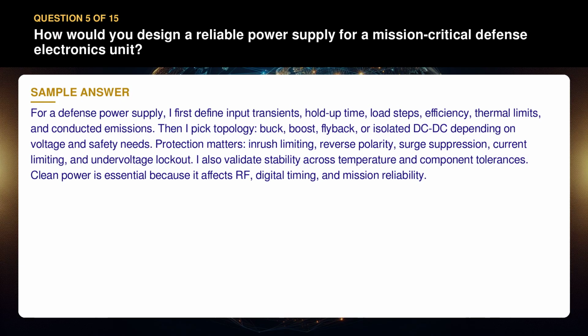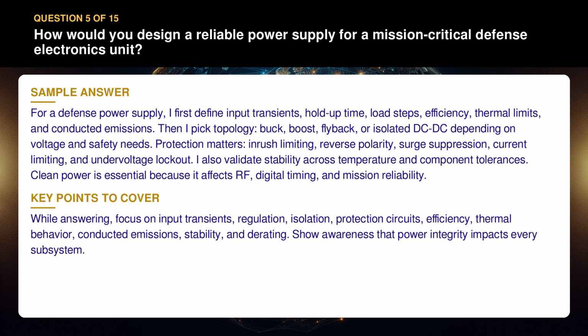Clean power is essential because it affects RF, digital timing, and mission reliability. While answering, focus on input transients, regulation, isolation, protection circuits, efficiency, thermal behavior, conducted emissions, stability, and derating. Show awareness that power integrity impacts every subsystem.